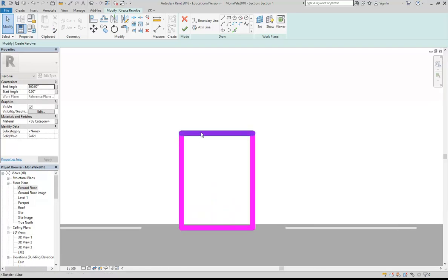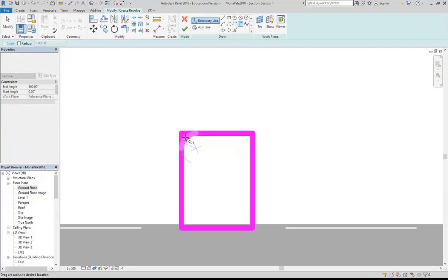So then the key here is that I'm going to round off the corners. And I'll just leave it sitting on the ground. I won't even worry about doing legs just yet. We can put legs in later, but I'll just leave it without them for now. So I'm going to use fillet arc up in the draw panel there. It's the second last button in that second row. I'm going to choose the two lines that I want rounded, and then just place the curve between them.